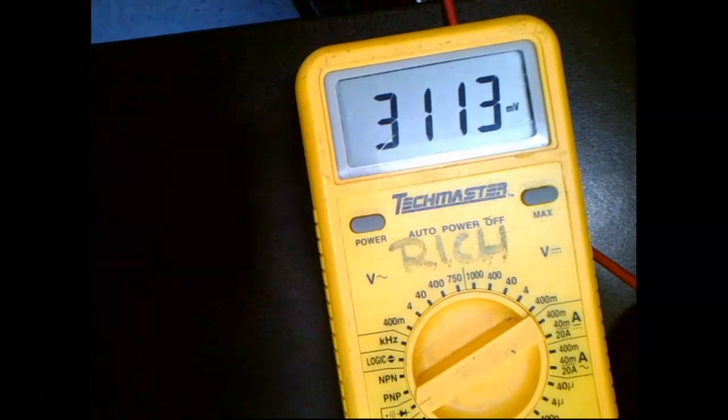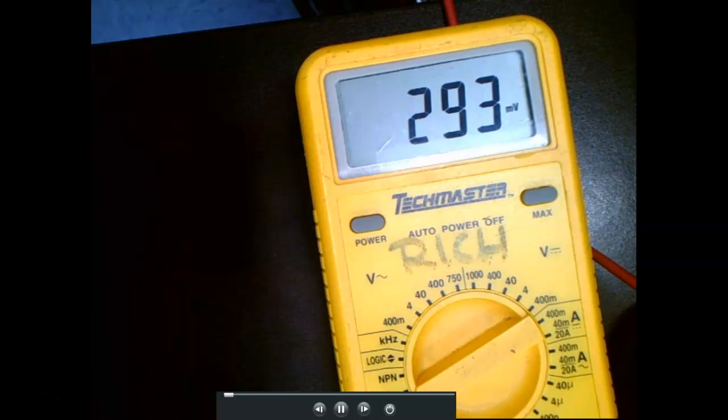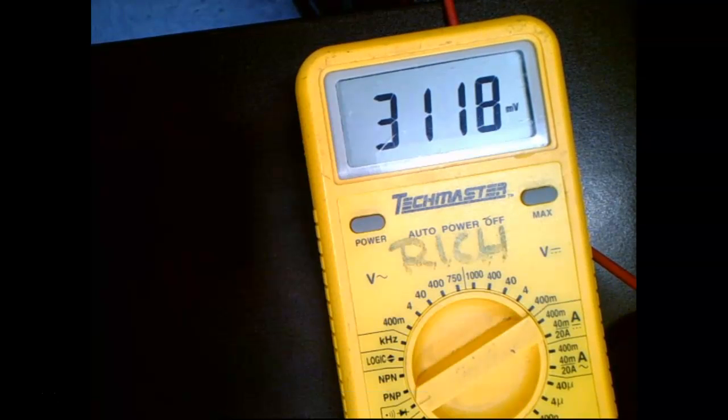I'm going to put this on the diode scale and measure it. So this is forward bias. It's measuring around 300 millivolts forward bias. And then when I flip it around, it's showing me that. So what type of diode is this? Around 300 millivolts. 700 millivolts is what? Silicon, right? And around 300 millivolts is germanium, right?